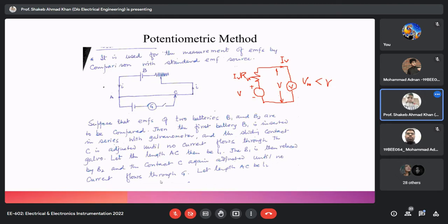Well, that is not quite so. Power dissipation is a problem in a potentiometer. So we have to have this resistance here. We are putting this resistance just to control this current, so that there is not excessive power dissipation and the wire does not get heated up. Can you recall what you have done in your laboratory using a potentiometer?